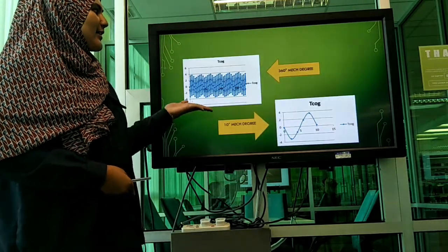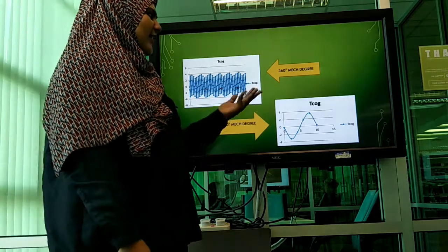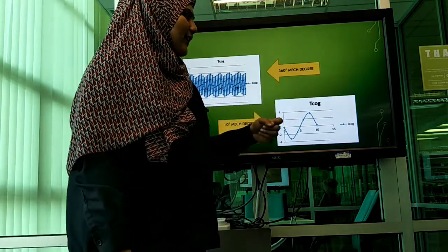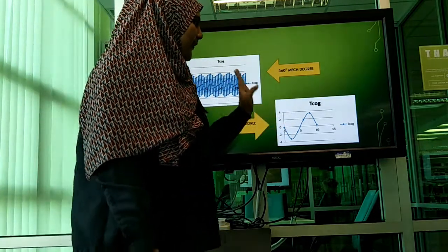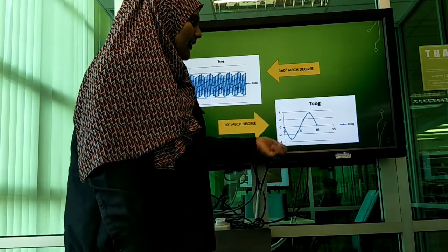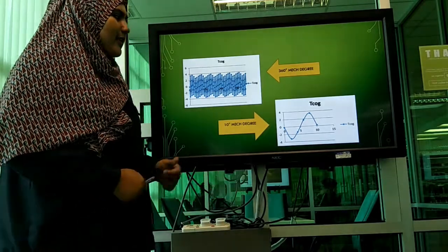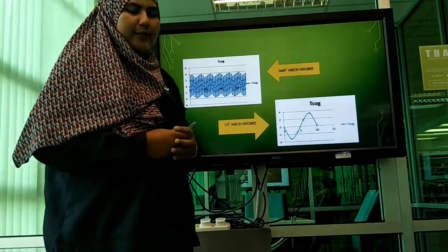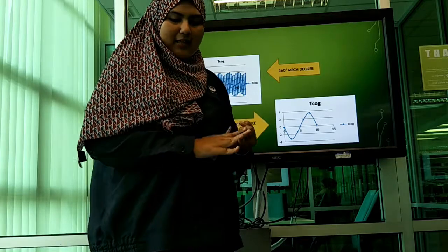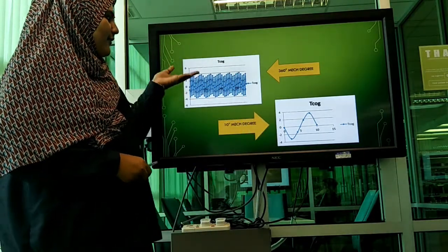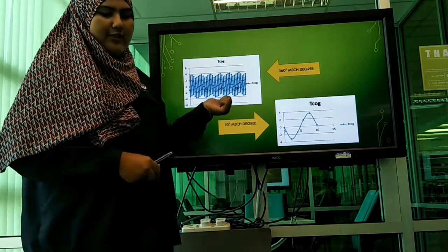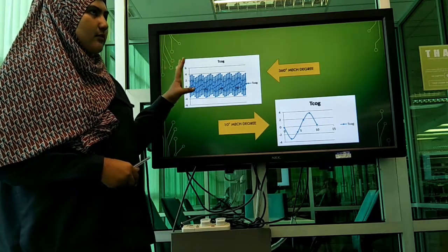Okay, this is the cogging torque for 360 mechanical degrees. Then we will take 10 degrees from here and it will be this cogging torque graph. This cogging torque will definitely produce output ripples, vibration and noise in the machine. The cogging torque varies as the rotational angle is different.